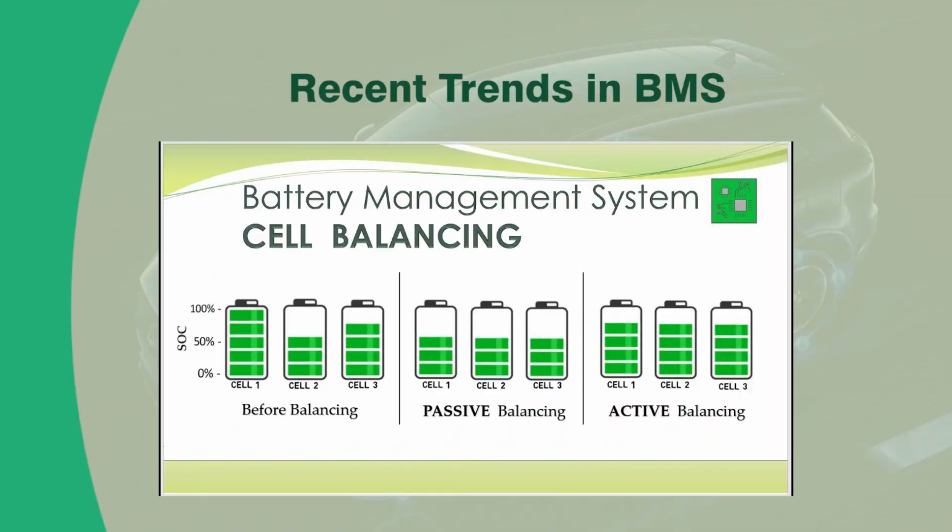Considering the performance, active cell balancing is very good, because in active cell balancing we generally use an isolated DC-DC converter, so that the power dissipation can be minimized. So there is a research opportunity in the active cell balancing design for the battery packs.